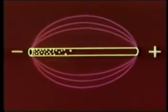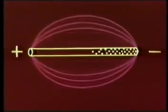When the voltage is of this polarity, the field is in this direction. When the polarity reverses, the field builds to a maximum in the opposite direction. This is known as the E field. The E and the H fields thus build and collapse 90 degrees out of phase with each other and constitute the antenna's immediate field. This immediate field produces the radiating wave pattern.